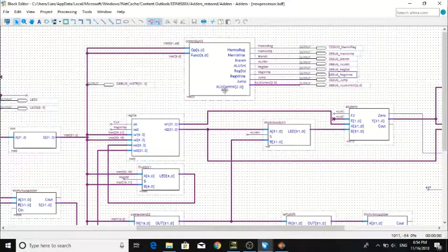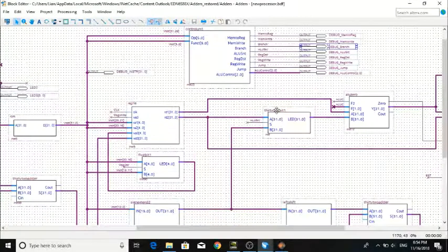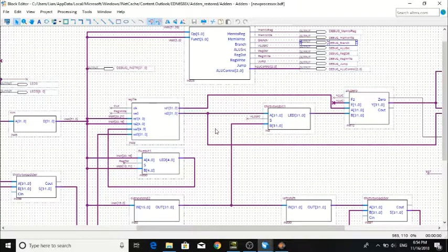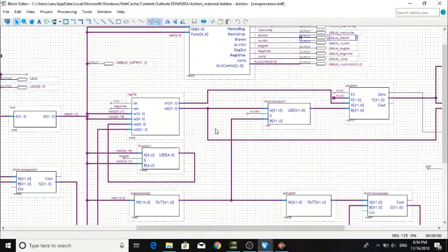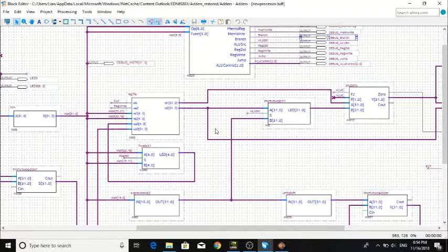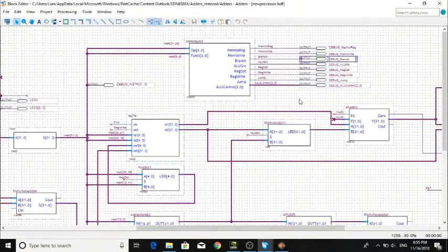This is the branch on equal instruction. The control unit decodes the operation code from the ROM. The control unit will then send a high input to the branch and the ALU operation. There needs to be a high input in the ALU operation, as there needs to be a conditional check. This is specifically when the data in the 2 registers are equal. As these are the only 2 components needed in the branch on equal instructions, the other components will have a low input.